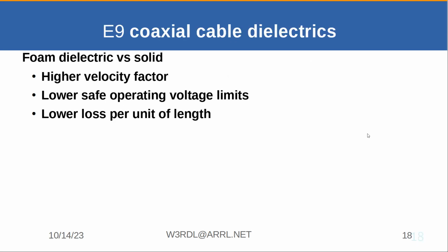Okay, so foam versus solid dielectric. Foam dielectric has a higher velocity factor. It has less loss. The disadvantage is it has a lower operating voltage. In other words, it will arc over at a lower voltage than a solid dielectric. I don't know how that's necessarily a big problem unless you're talking about putting a lot of power through it,